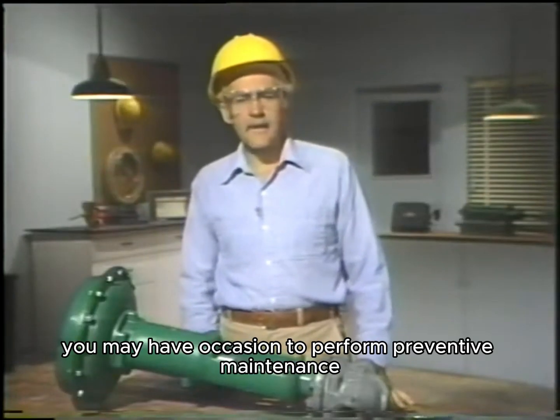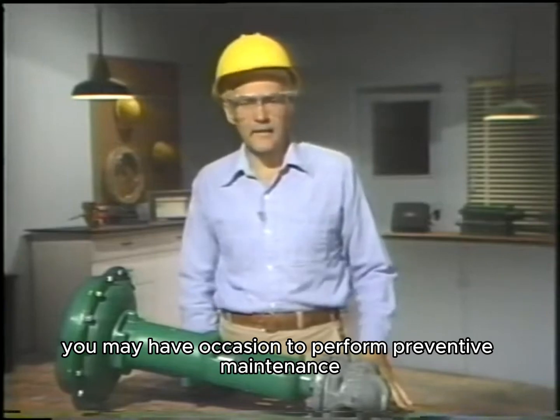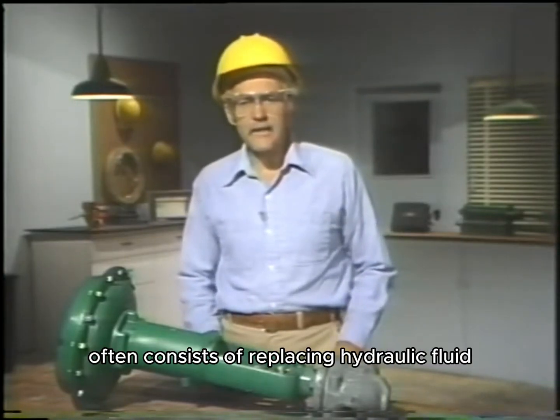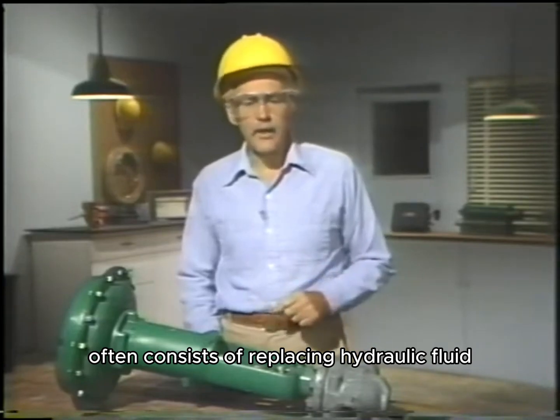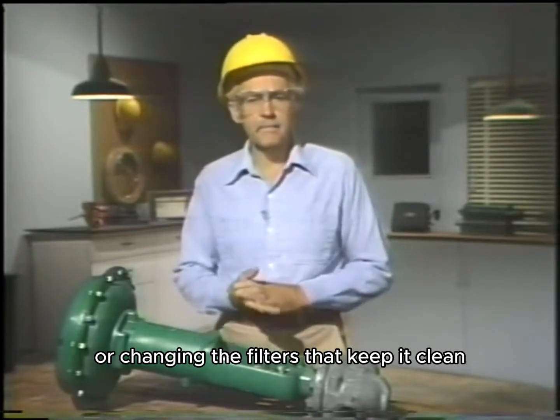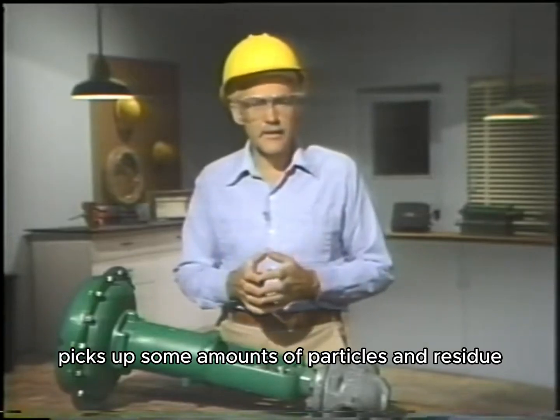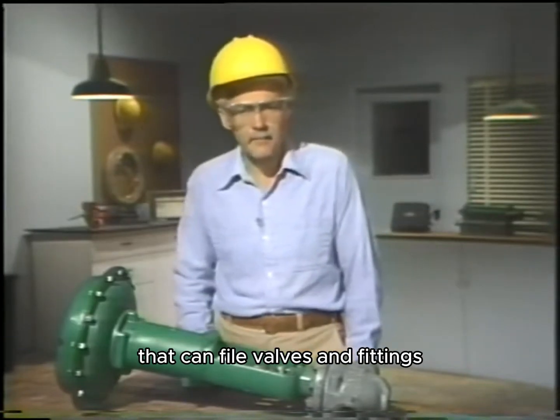On the job, you may have occasion to perform preventive maintenance or repairs to hydraulic actuators. Preventive maintenance often consists of replacing hydraulic fluid or changing the filters that keep it clean. The fluid inevitably picks up some amounts of particles and residue that can foul valves and fittings.